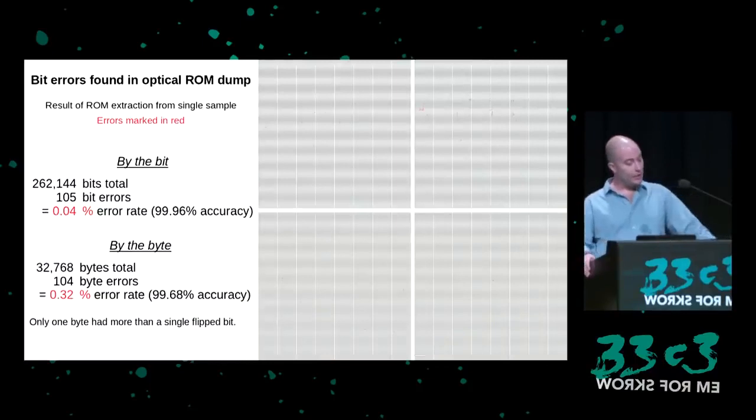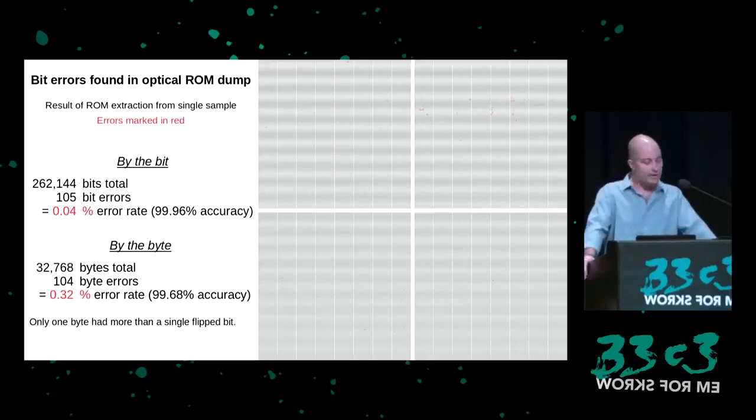Since we can execute code on the ACP and receive a response, we can read the ROM to have its contents without any of the errors that were introduced during the optical extraction process. Comparing the results of the optical ROM extraction with a proper dump, we can see how many errors were in the optical extraction. Overall, the optical extraction was quite good. It was, after all, good enough to understand the software and get us to this point.